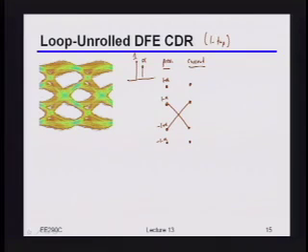Okay? So this particular type of transition turns out to be a fairly simple one, because notice this center point here, which, remember, at the end of the day, you're looking for where the ups balance with the downs. That's conceptually always happening when those edges cross over with each other. That center point is centered around the 0 threshold, because notice the swing for both of them is symmetric around the 0 point. Okay? Well, as we said, this was for a clock pattern.